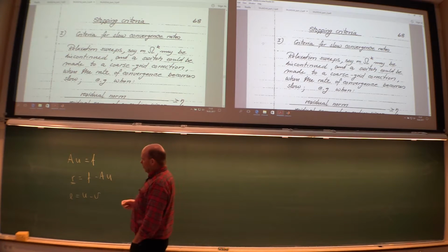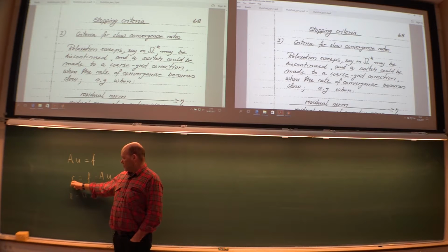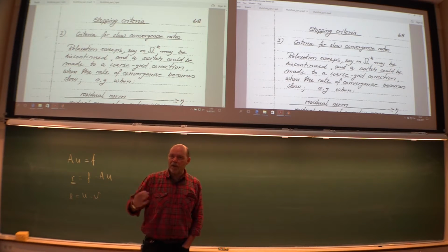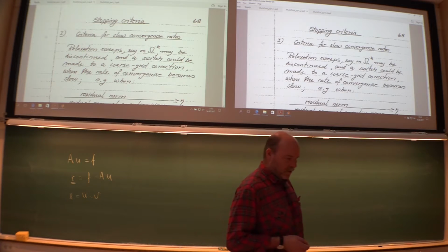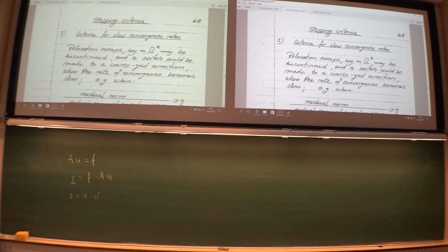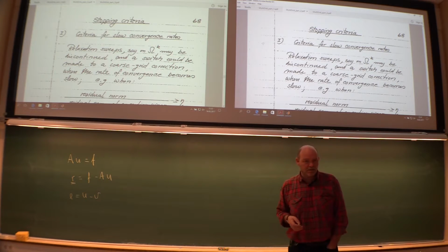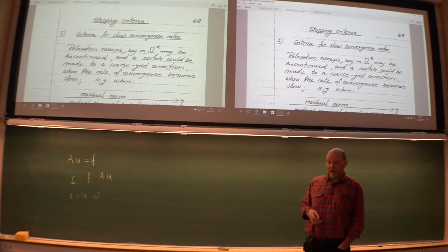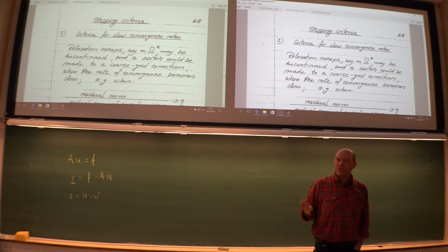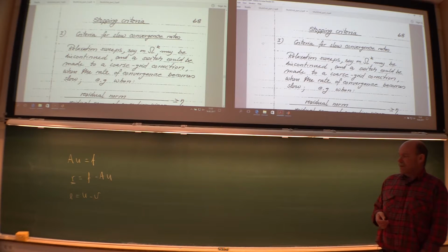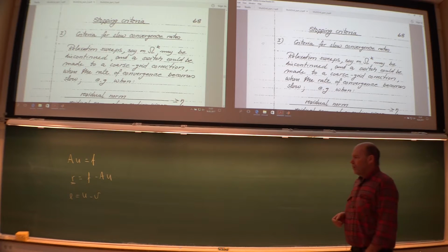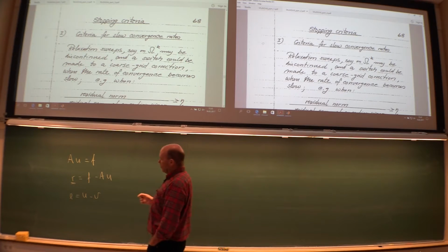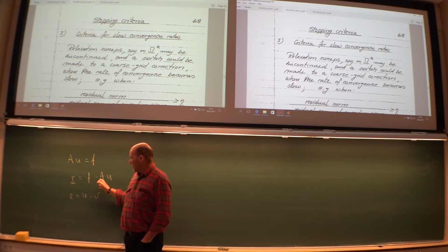So typically what you do is look at the reduction of the residuals depending on how many iterations or V-cycles. And when it has been reduced by, say, 3 or 4 decades, meaning a factor of 1,000 or a factor of 10,000, then you say, I'm satisfied. But then you really don't know if the error is small. So what would have been nice is to have an indicator with a little bit of physics in it. But that depends on your problem.